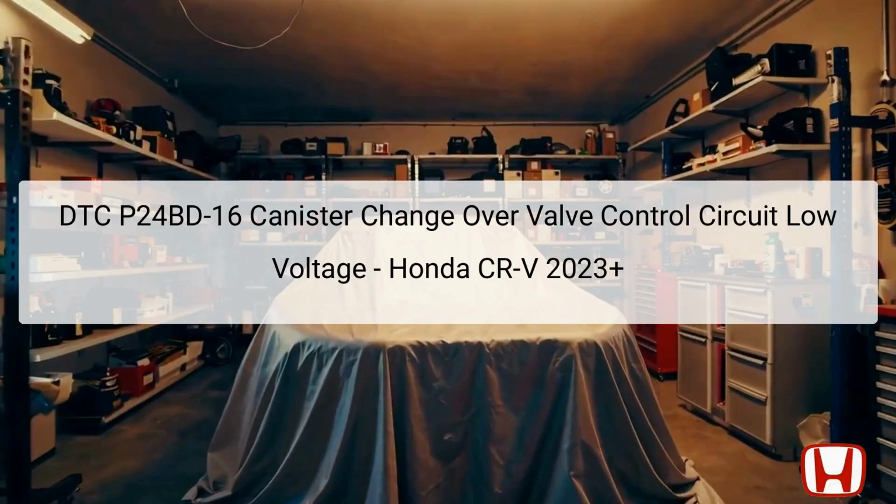The DTC code P24BD-16 refers to a diagnostic trouble code specifically indicating a low voltage issue within the canister changeover valve control circuit. This error code is significant because it affects the functionality of the canister changeover valve, CCV, which is crucial for managing fuel evaporation and maintaining emissions control.